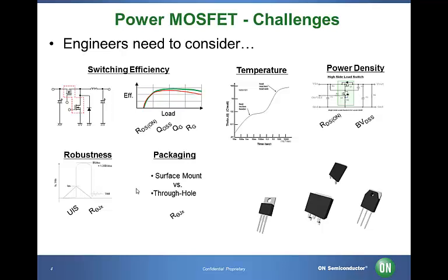Switching speed correlates to the total gate charge that needs to be charged or discharged in the gate drive circuit. It's denoted as QG. It is critical to choose whether you need to minimize the on resistance or to accommodate fast switching speed by keeping the gate charge under control when designing a MOSFET. For the development engineer of the application, it is important to choose the optimum MOSFET and trade off on resistance power loss versus switching power loss for the given application.